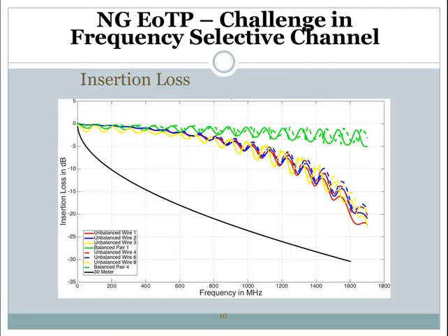under the unbalanced mode, where each wire is excited by its own excitation source, and the outer shield is used as a common ground. We can see that this insertion loss is not so good as the balanced mode, but we do have more channels available for the transmission.